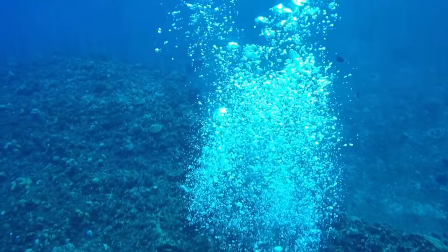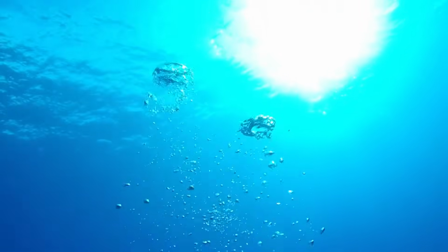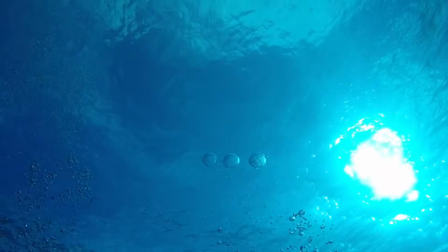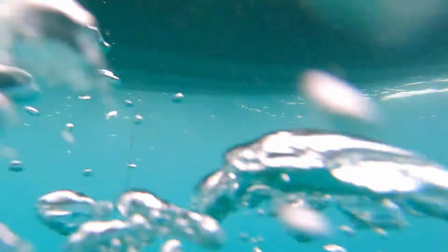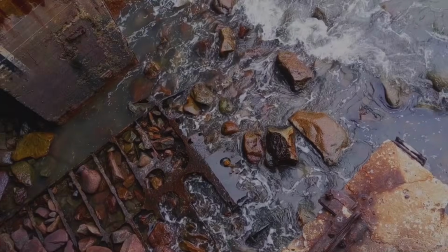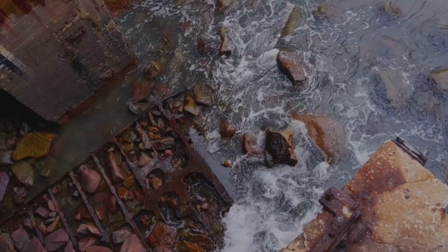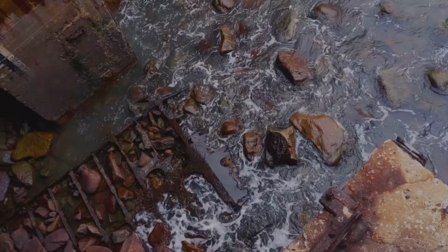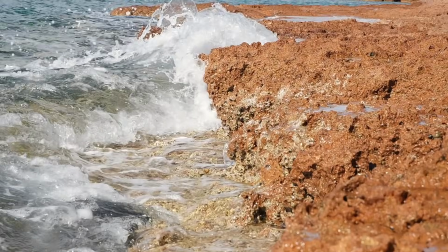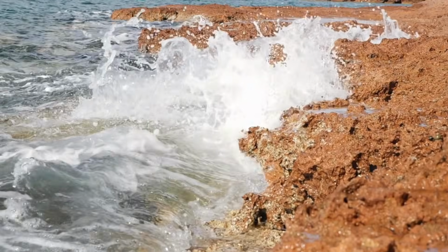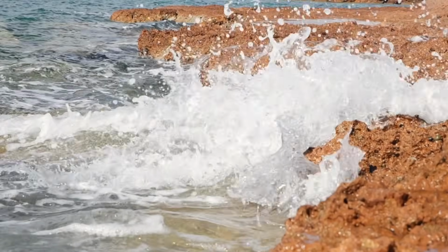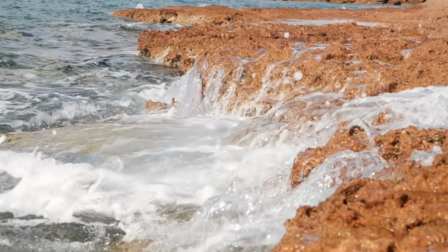This same turbulence also causes intense cavitation. As the water moves at high velocities over uneven surfaces, the pressure can drop so low that the water literally boils at room temperature, creating tiny vapor bubbles. When these bubbles move into higher pressure areas, they collapse with enough force to pit and erode solid steel. In a dam failure, cavitation can eat away at the remaining structure of the dam, even as it is failing, accelerating the collapse in a way that is notoriously hard to predict.